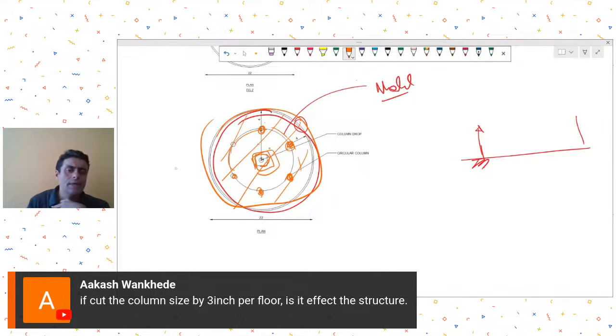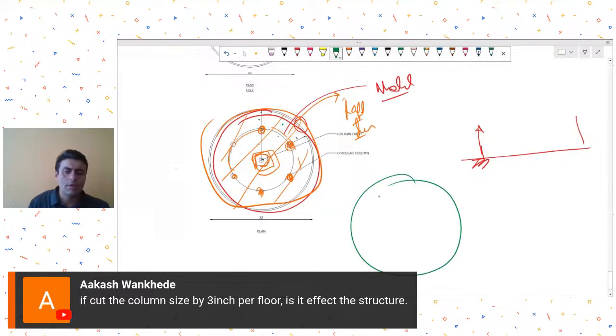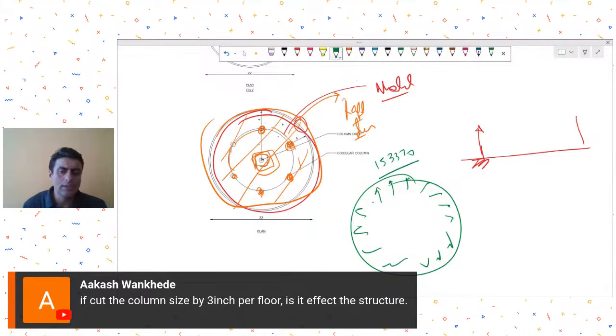Okay, and then you can take this model for raft analysis design also. So I'll suggest you to do this thing in two parts. First, you just make a wall model, because the effect of the slab load is not going to affect your wall reinforcement as such. So therefore, I'm suggesting you first make only a wall model, apply the water pressures, and find out the wall reinforcement requirements. Do all the IS 3370 checks over there. There are a lot of checks that you need to do.